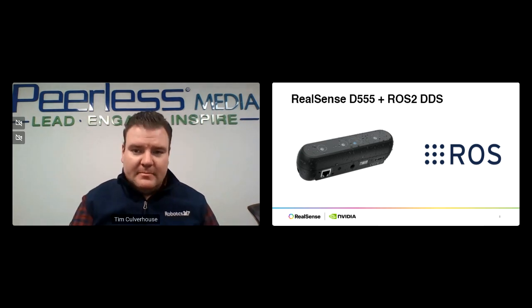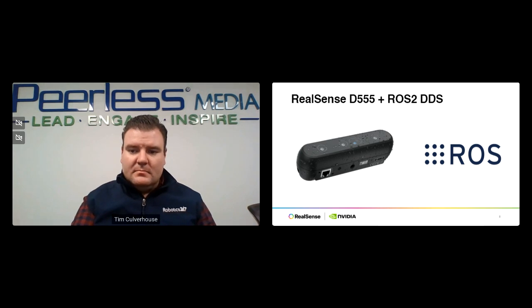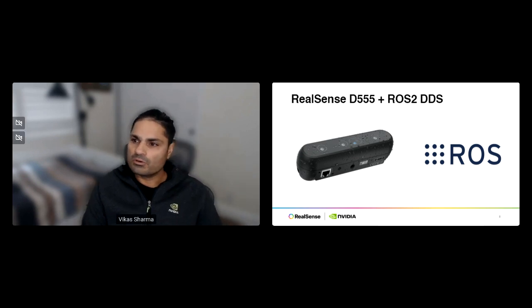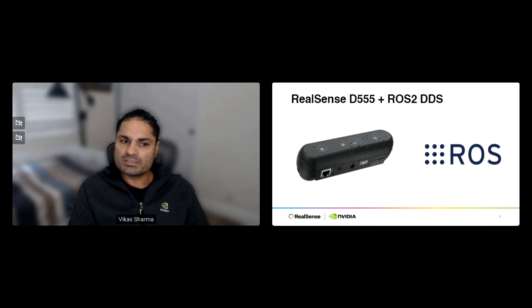Yeah, so as far as the noise model goes, this noise model was released with Isaac Sim 5. So if you download Isaac Sim 5 and look at the documentation, you can get the details of what parameters are exposed to mimic the noise in the depth map. I think this is also a question being asked in the Q&A: this depth noise model is a generic model which can be used to mimic noise for any stereo camera.